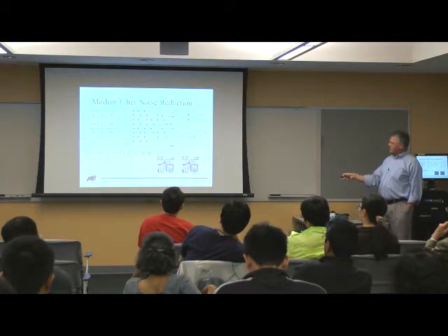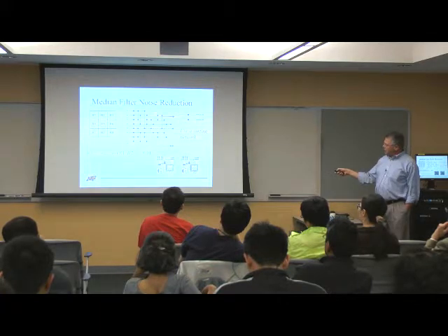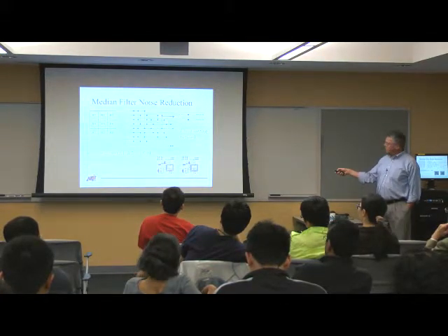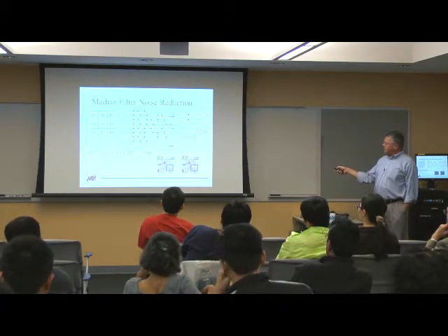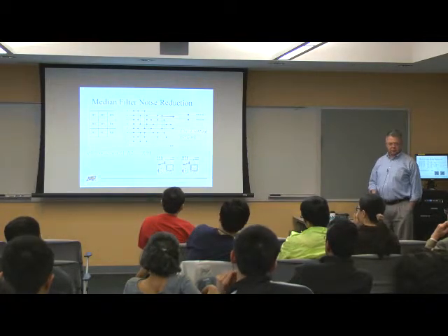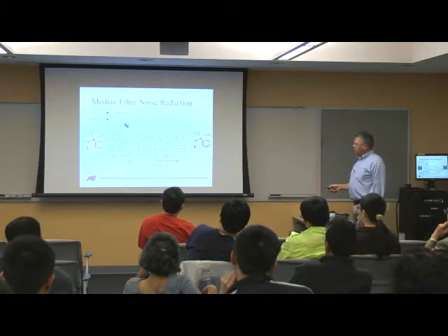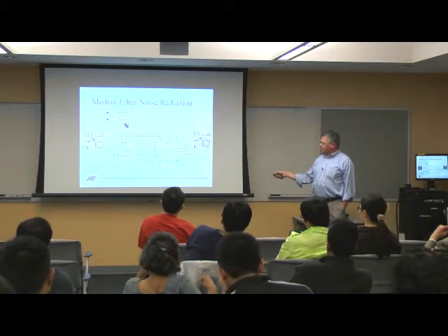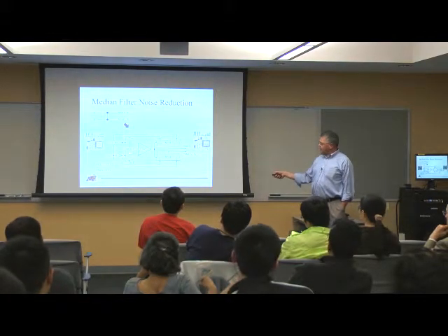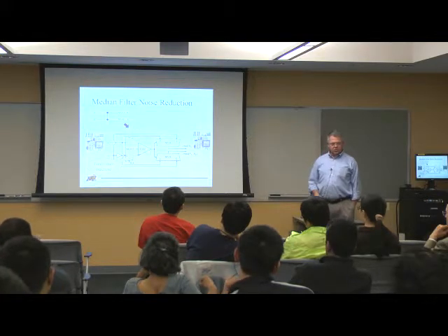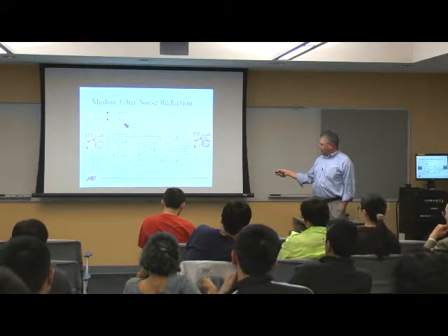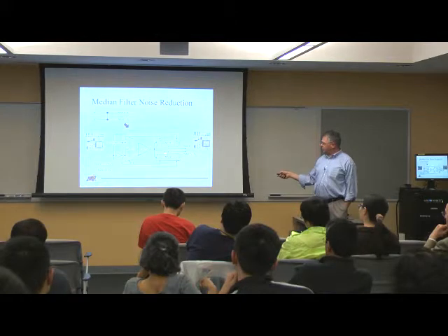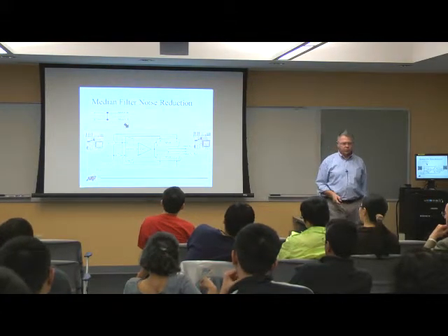The noise filter, I have a similar kind of thing. This is a median selector. The key operation here is this select here, where I have two inputs coming in. I send the min on the top and the max on the bottom. So it's a sorting network. Each one of these sorters looks something like this, where I have a stochastic subtractor. I have this finite state machine to do the thresholding, and then I select one or the other stochastically with this multiplexer. So I have the pixels coming in, run through here, and I have the pixels going out through this sorter.